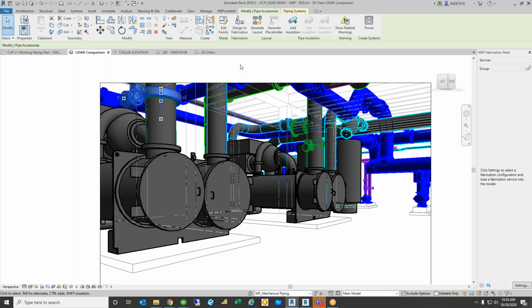I just want to add a comment, this is John, and I think why this is all applicable to our subgroup in particular. If you're a user and you're going to try to connect into your existing chilled water system, and you want to minimize the amount of work that's done, especially hot work on the site, having a lot of this prefabbed is a way to minimize that interaction on site and reduce your risk. So level 350 brings you to the level where you can have that done.